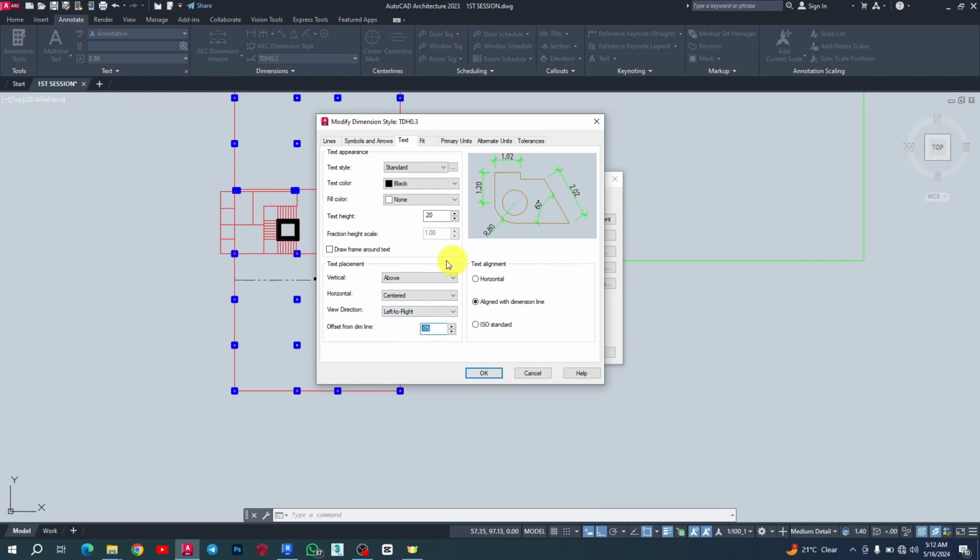And then above the line, you always have to get the text a little bit up, not lying on the line. So you want to take this dimension a little bit up so that the text is not lying directly on the line. You can go with what works for you there. So I usually go 0.05.